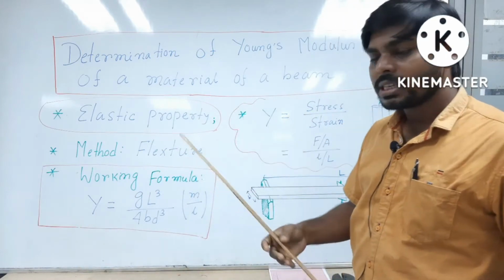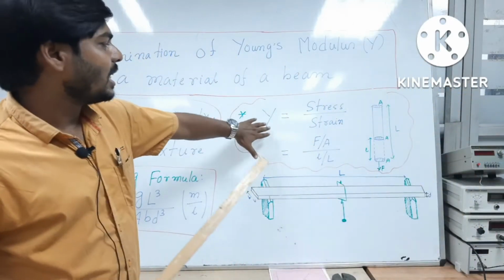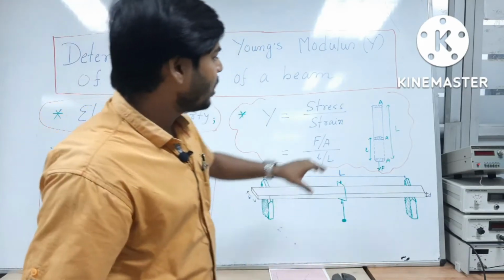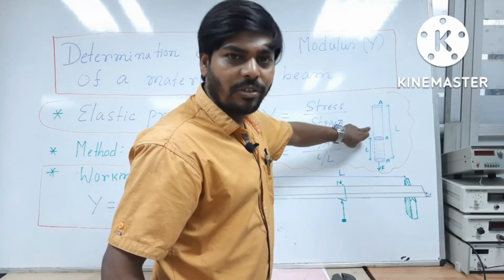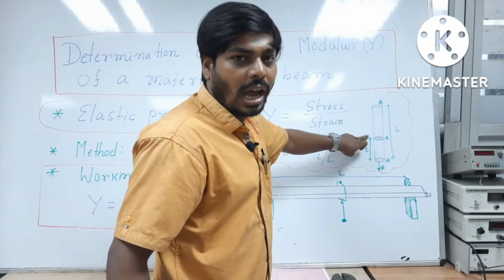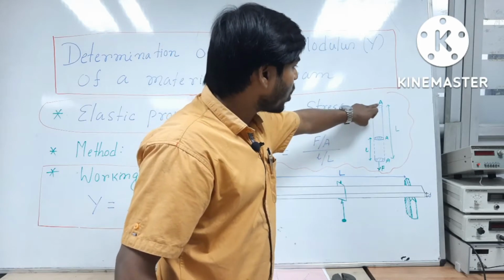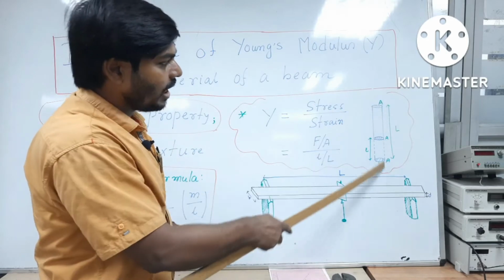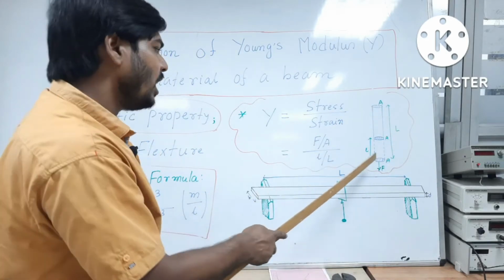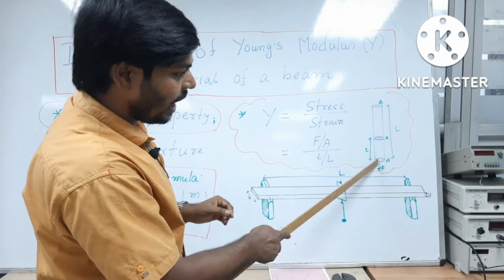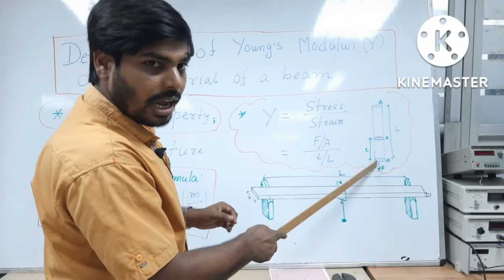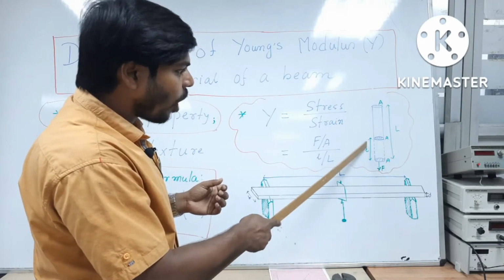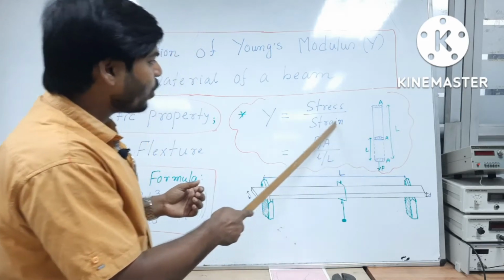What is the Young modulus? As you know that Young modulus is defined as stress by strain. For a moment consider it is a material, maybe it is a wire of iron or steel whose cross section area is A, and let us say its length is capital L. Now, if we apply a force F along this direction and consider due to this force there is an elongation of small l, then as we know what is the strain?